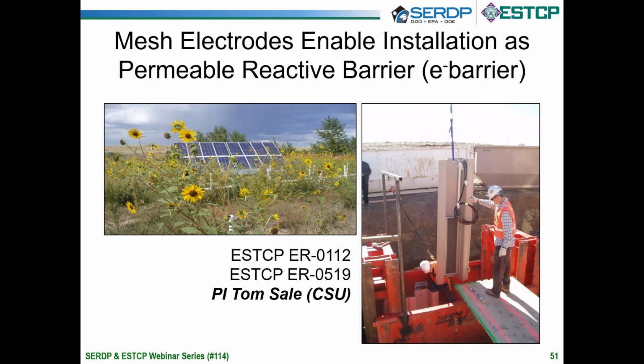And then you can sink that basically into a trench and backfill it and install monitoring devices, for instance, and just wait for the contaminated water to pass through. And you can run that very sustainably by solar power, for instance. This was a project in Colorado where we do have a lot of sun. And if you're worried about too much above ground infrastructure, then you can eliminate that too and just use power from the wall, but you can run this with solar power.